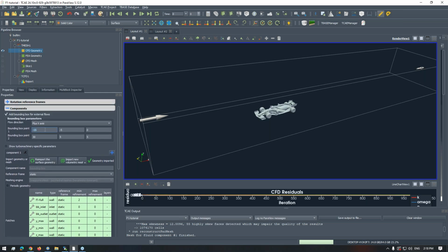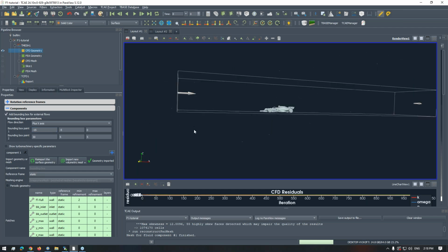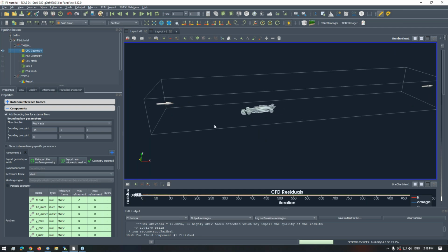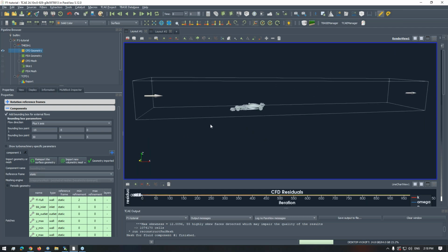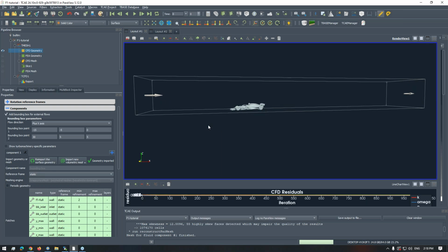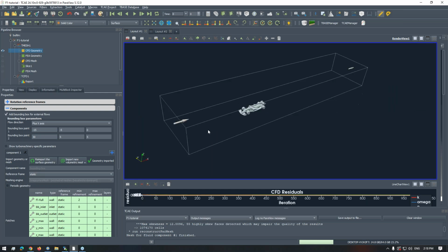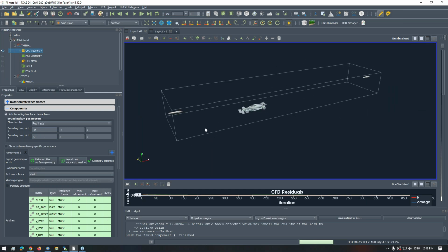So you say what points are defining this virtual tunnel, which is completely up to you. Some people say that a bigger virtual tunnel leads to a little bit more accurate results. But in the beginning we like to take it simple, play simple. So maybe this is lesson number 2. I would like to recommend starting with simple models.